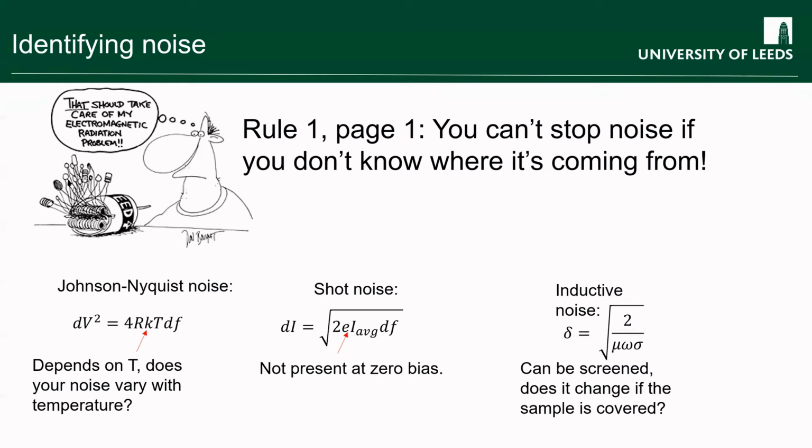So by some relatively simple checks of checking with frequency, checking with bias, checking with temperature, you can make a big step to trace where your noise is being generated, and therefore think about an appropriate way of fixing it.